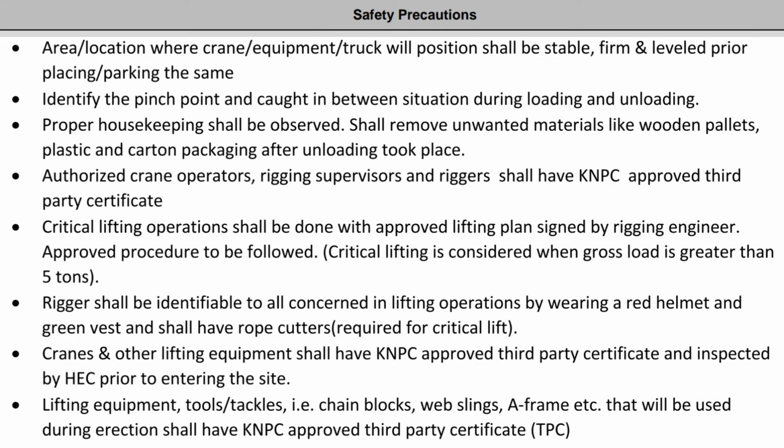Equipment area, location where crane, equipment, truck parking or position shall be stable, firm and leveled prior to placing. Identify the pinch point and caught-in-between situations during loading and unloading. Proper housekeeping shall be observed. Shall remove unwanted materials like wooden pallets, plastic and carton packaging after unloading takes place.